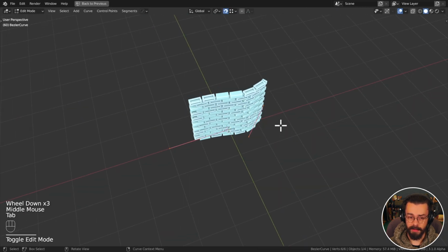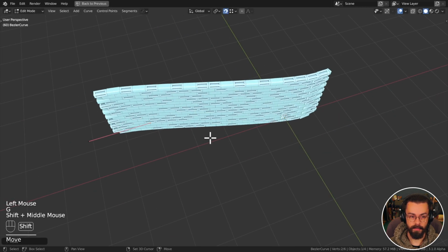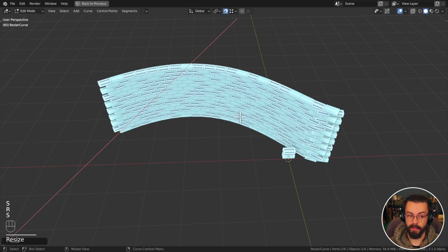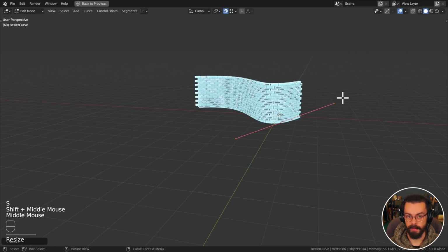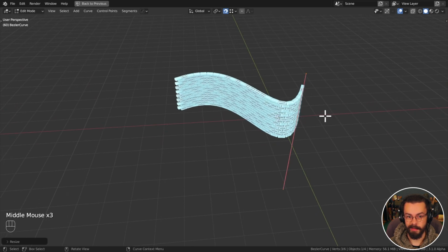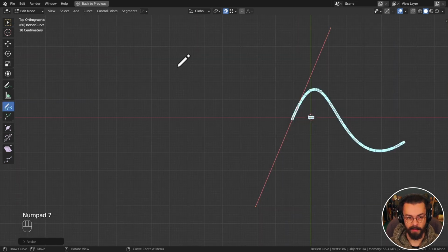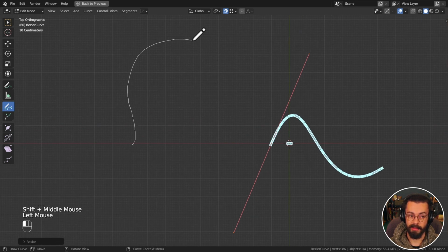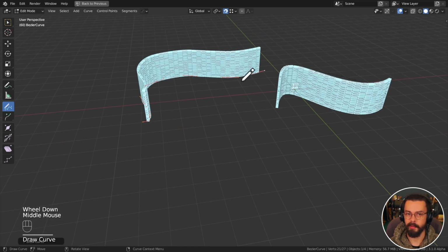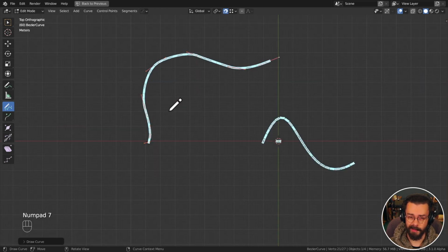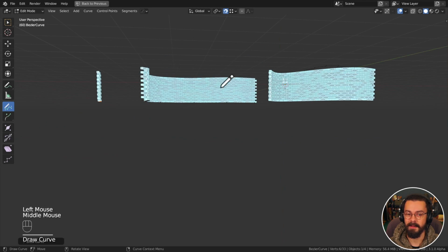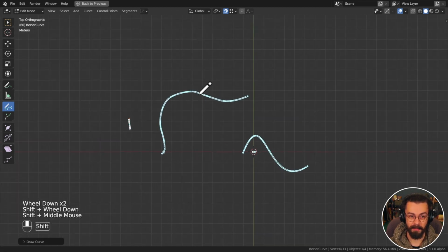Why is this useful? Well, because it means I can come in, grab my spline, make it a little bit longer, make it curved. If you want custom curved walls, then you can do something like that. Now, another thing which is extra fun is if you go into your tool shelf, come down on the left-hand side, you can find a Draw Freehand Spline tool. If I go into Z here, now this one, I do really need to bug fix. If you have an even number of splines, for some reason the spacing gets mixed up. So I do need to just do a little bit of a bug fix at some point. But as long as you just make a third one, you're fine. You get that offset back.